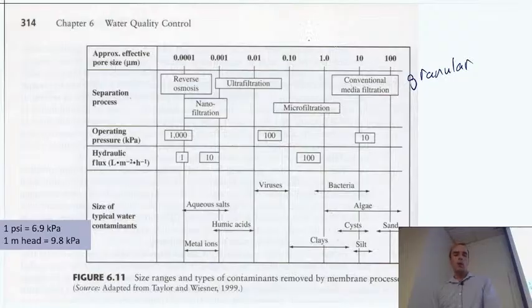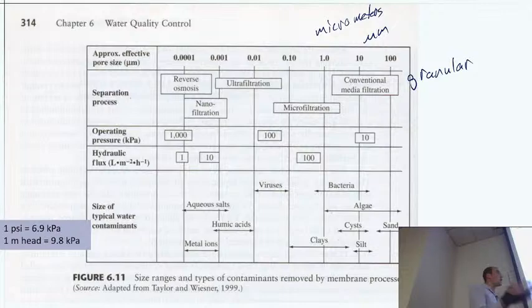This will remove particles, and this is micrometers here, or that. So a conventional sand media filter can remove things down to a little over a micrometer. And again, that's not necessarily the size exclusion, some of that is adsorption and stuff. So we can maybe remove some bacteria with a conventional filter, but we're certainly not relying on it to get all bacteria.